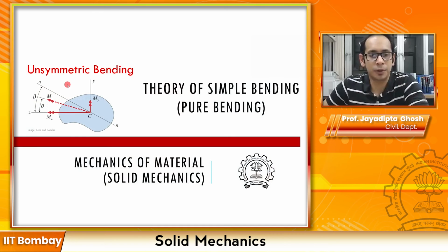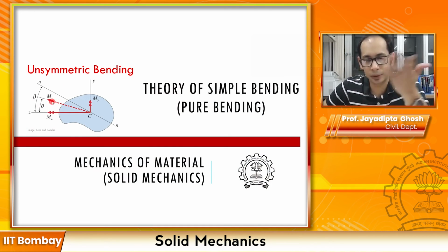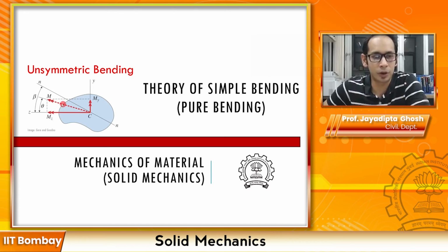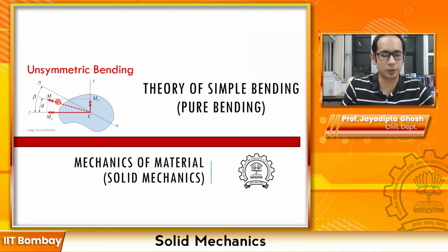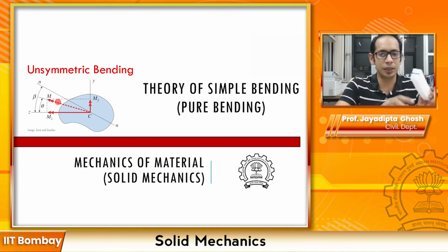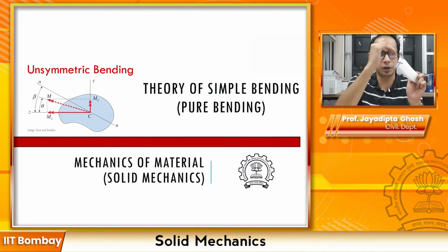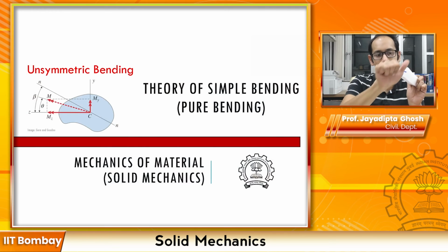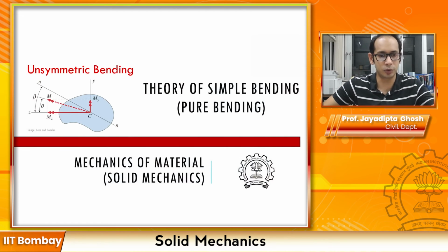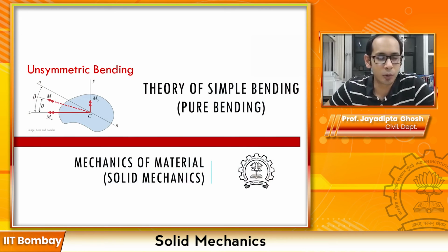Now don't be confused by these double arrows. Moments like couples and torques can also be represented by these double arrows. All it means is that your thumb points towards that. So the moment I'm bending like this, that means my moment is pointing towards that. If I am supposed to represent the moment in terms of a straight line instead of the curved arrow we always see, it is a straight line along where my thumb is pointing with a double arrow. That means that I'm trying to bend about this axis over here, about that arbitrary axis I'm talking about. So this is what you see over here, that this moment is acting like that.